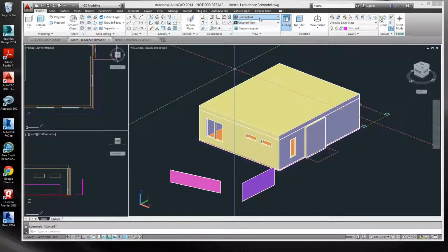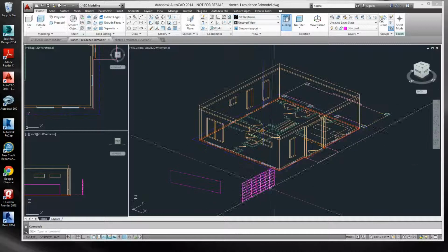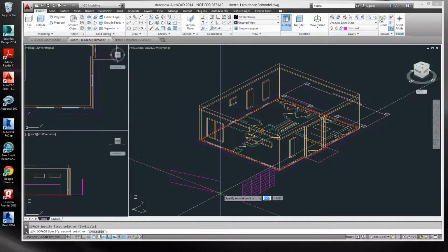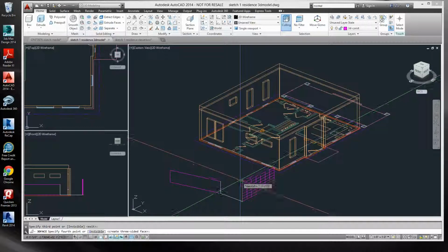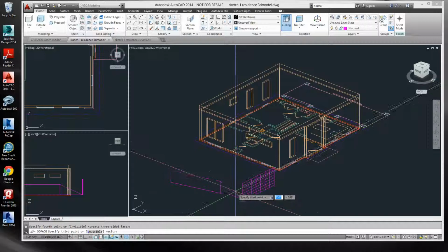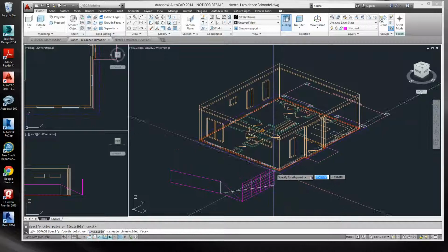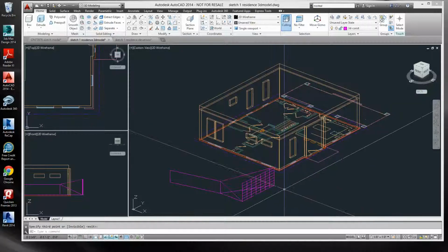And remember, if I go into the 2D wireframe, I'll see the difference between an extruded line, which meshes out with subdivisions, and a line with a thickness. And then the third one that I made, remember, was 3DF. I can just pick the 4 points, or 3. If I hit enter after 3, it makes me a triangle. If I hit enter after 4, or if I don't hit enter and just pick 4 points, then it makes a 4-pointed face, and it'll snap to anything regardless of what my UCS is, because it's independent of the UCS. That's the quick surfaces, and next we're going to talk about normals.